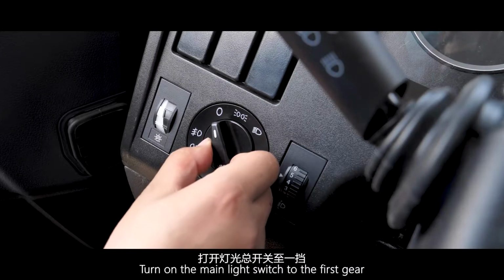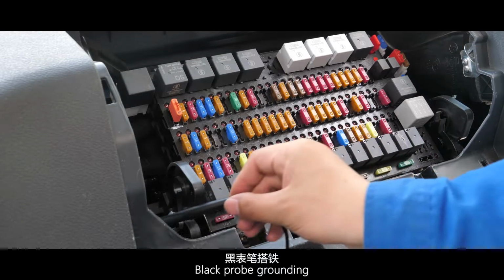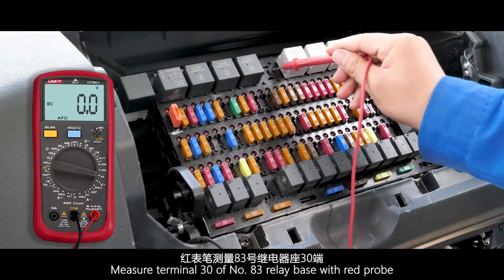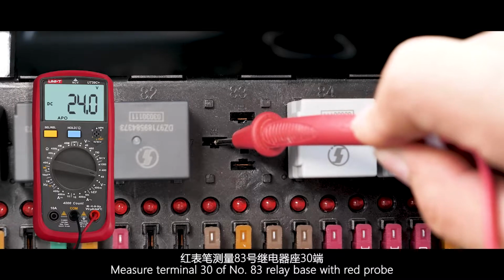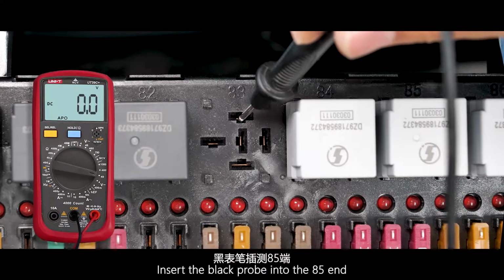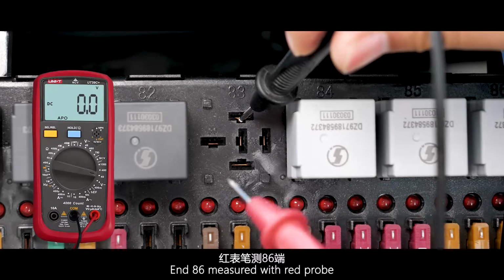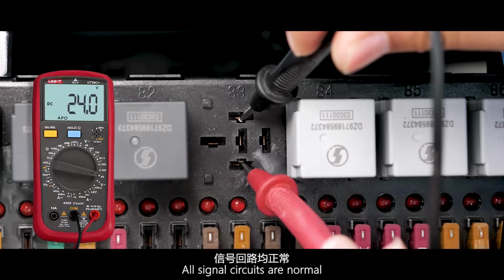Turn on the main light switch to the first gear. Black probe grounding. Measure terminal 30 of the number 83 relay base with the red probe. The input voltage is normal. Insert the black probe into the 85 end and measure 86 with the red probe. All signal circuits are normal.